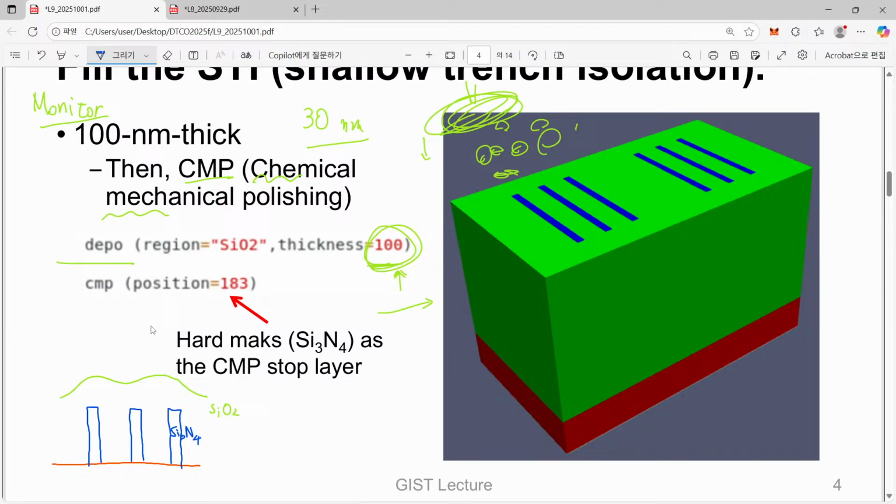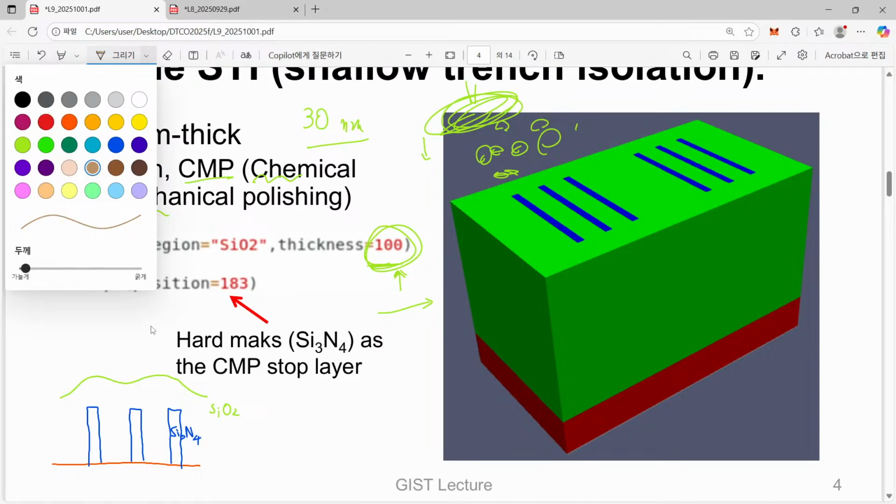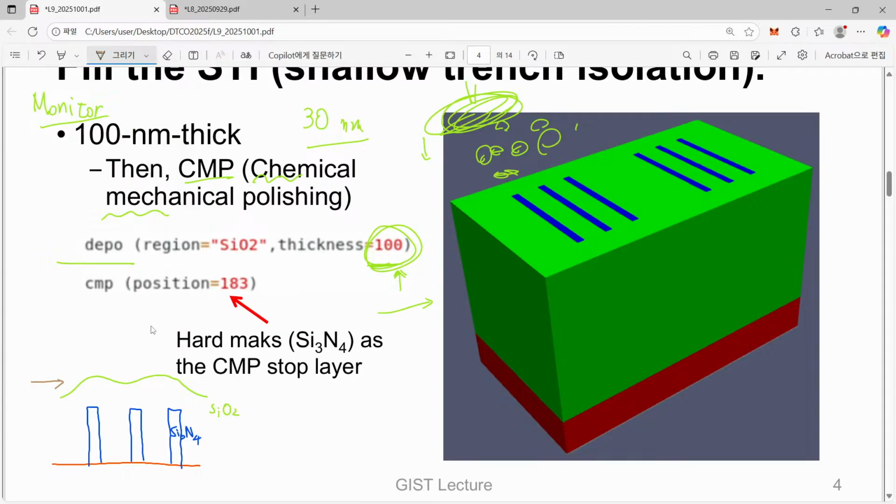When we have this structure, then obviously when the level of our CMP is around this structure, the polishing is mainly determined by the rate of silicon dioxide. So it is almost constant. And let's think about the level around here. If its front is shown here, then still we will have that of silicon dioxide. And if we touch this top surface, then what will happen?